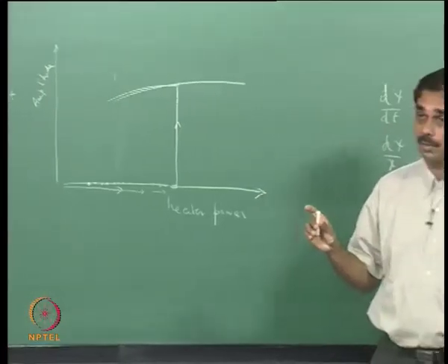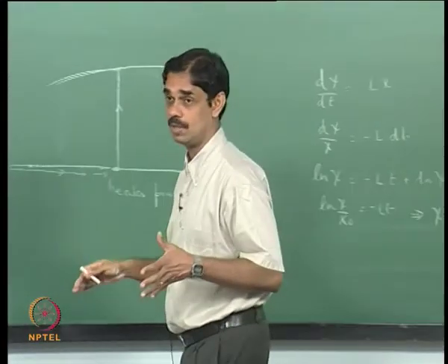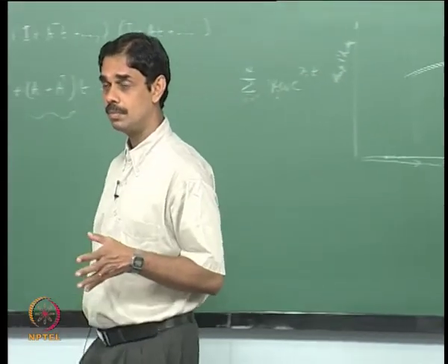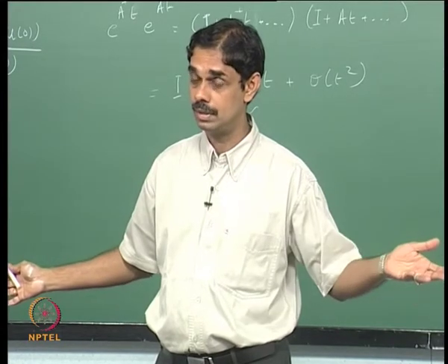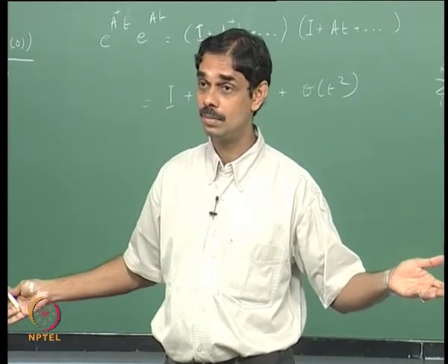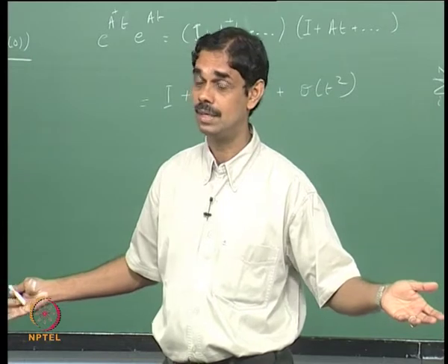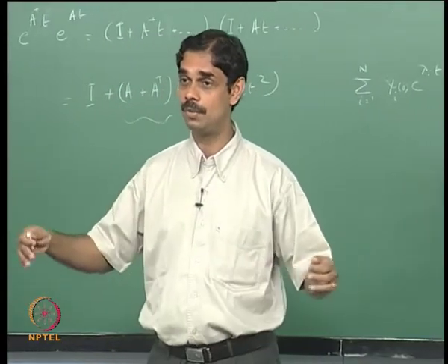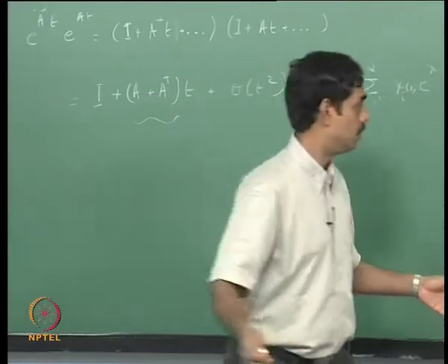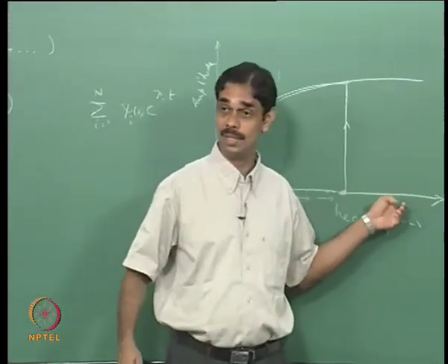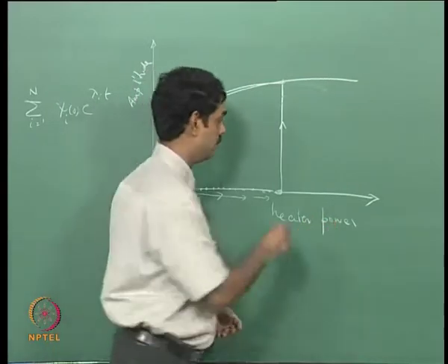In fact, in our Rijke tube, first let us look at what is stable versus what is unstable. You can have the Rijke tube, just have the base flow, that is a solution to the equations, right, isn't it? If there is no perturbation, your solution will be trivially satisfied. If u prime, p prime, q prime, everything is 0, won't your equations be satisfied? It will be, but you can't have the solution here once the heater power is jacked up.